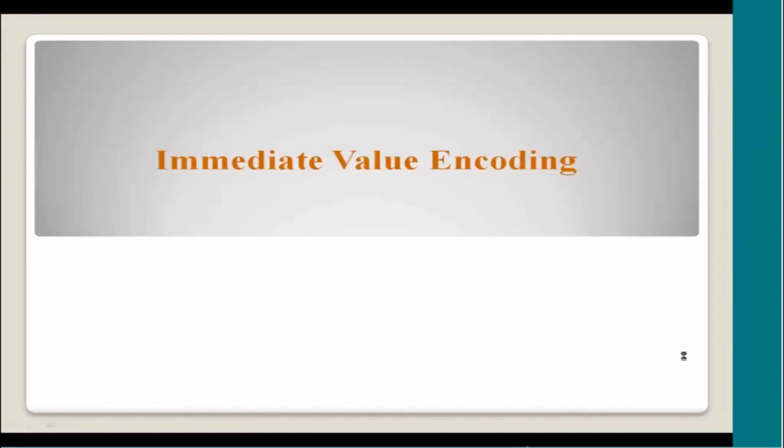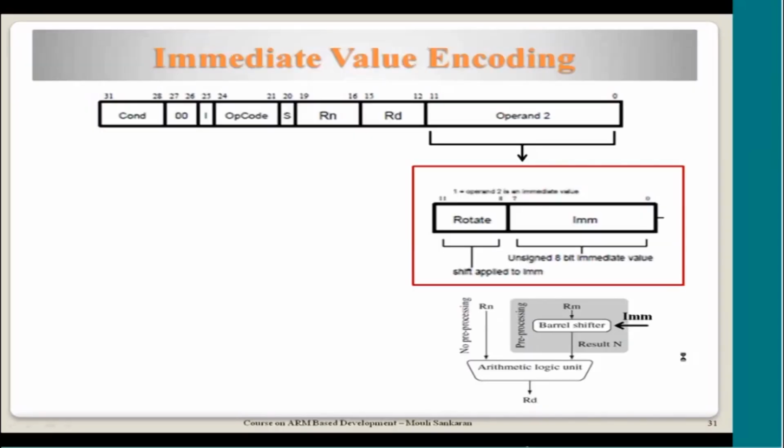so these are all about the combination where one of the operands was coming from Rm. Now another combination is when everything is mentioned as an immediate value. So it's a special condition. That means this Rm is not used at all, because if you see in this combination there is no Rm mentioned here, and this is actually the I bit.